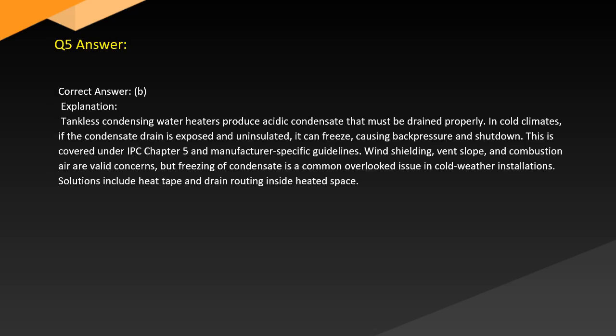Answer. Correct answer B. Explanation. Tankless condensing water heaters produce acidic condensate that must be drained properly. In cold climates, if the condensate drain is exposed and uninsulated, it can freeze, causing back pressure and shutdown.